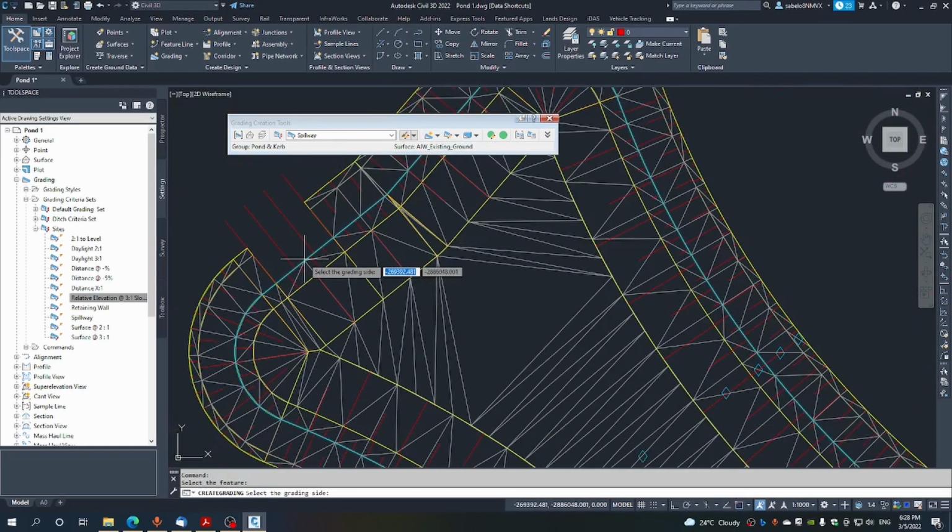We're selecting that feature line on that side. We will do it between there. Must accept that. And between there, I accept that. We will go for a distance of 1.5 meters. Gradient will be 0.